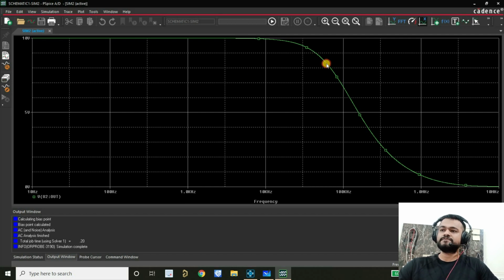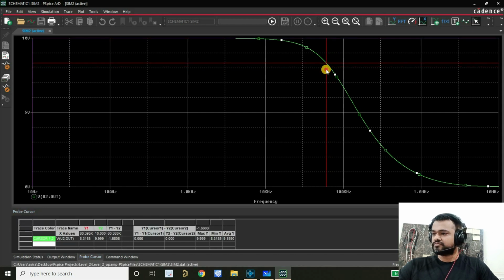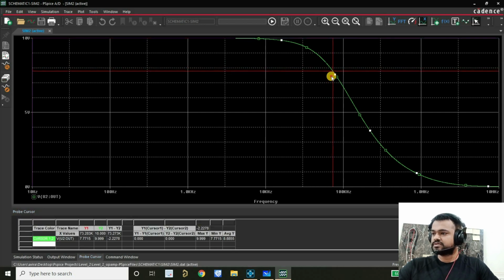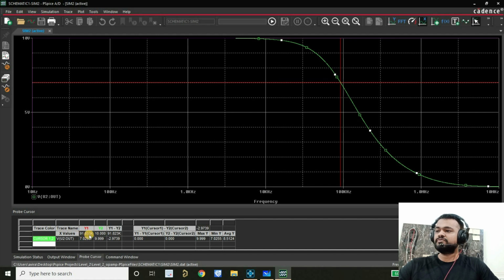But in the case of the inverting amplifier, if we go for 7 volt, it is 91.83k. Okay, and the hint is this is happening because of the feedback resistor in the source. So this is the difference, right? I just want you to put your answers in the comment section why this cutoff frequency for the non-inverting amplifier is higher than the inverting amplifier.